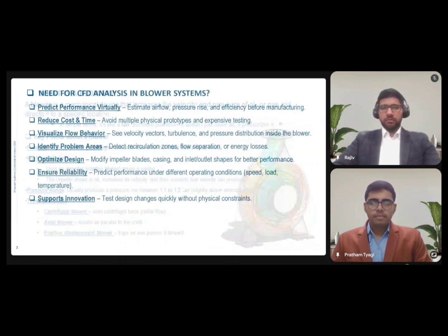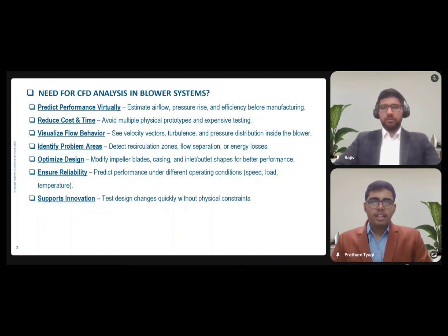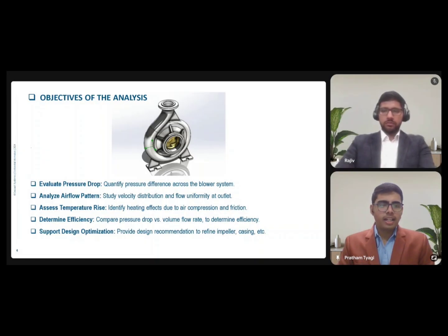Next up, we have the need for CFD analysis of a blower system, a general question. The main need for this analysis is to predict performance virtually, which supports reduction in cost and time. It helps us visualize flow behavior, identify problem areas such as recirculation zones, flow separation zones, and energy loss zones, optimize design changes and ensure reliability, and eventually supports innovation to test design changes quickly without any physical prototyping.